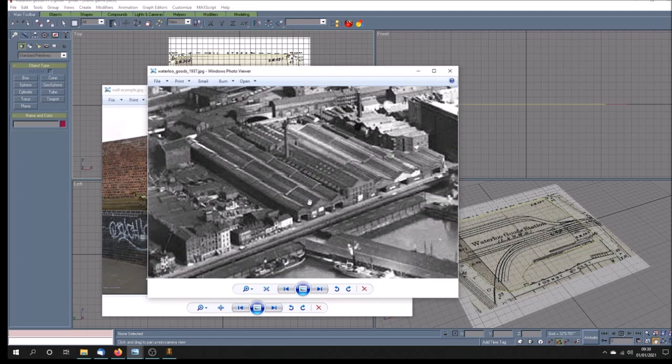So we're going to compromise. We're going to make it flat. It's not going to rise. If we put a road in there, it's going to conceal some of the wall as it climbs up to meet that road there, which will be determined by the bridge. If we put the bridge in there, we can always put a descent for the road to come down a bit to make this gradient less severe. So that's going to be all on the level. That's the only way I think I can do it.